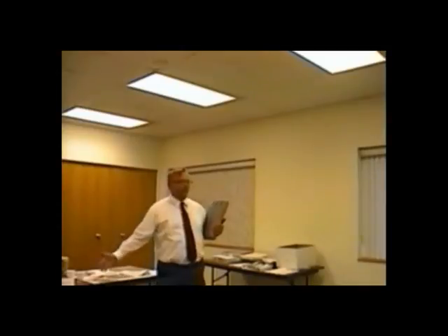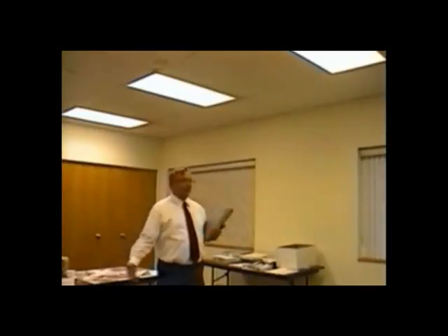Why are you messing around with charge? You say, gee, I don't know if the charge is correct. There's been 7 people out here before me. I don't know if I'm under. I don't know if I'm over, and my superheat's here, and I have to add a little bit here. Now I got to let it run, and I have to go and take my inside temperature, and then I have to go and take my pressure again. I have to look at my high side for subcooling. 45 minutes minimum. That's if the conditions are right. If the house is cool, the house has got to be cool. So forget it. We don't teach that anymore.